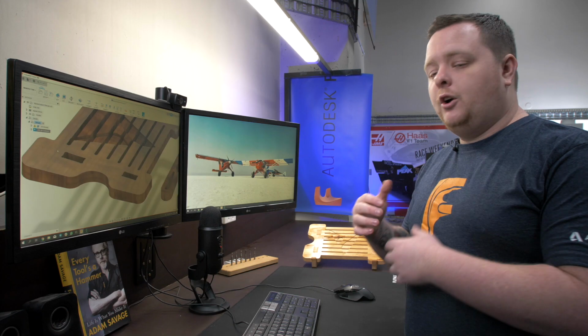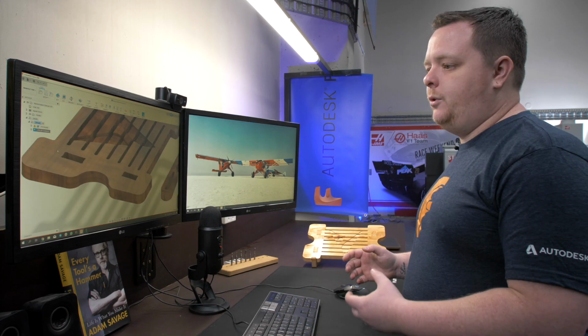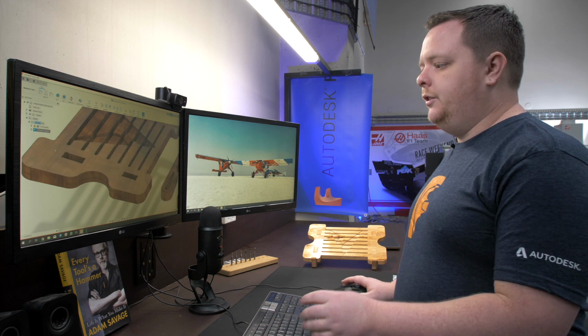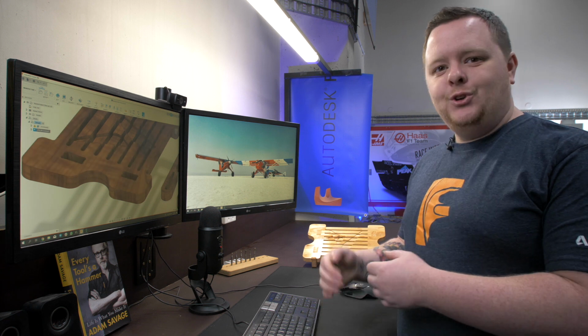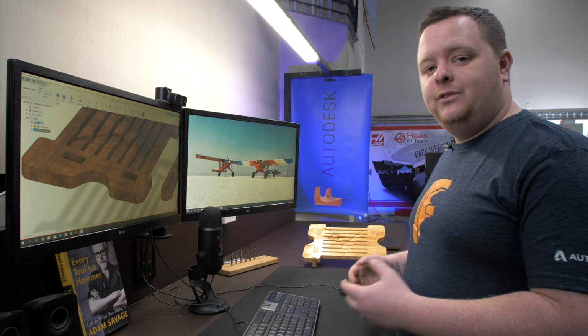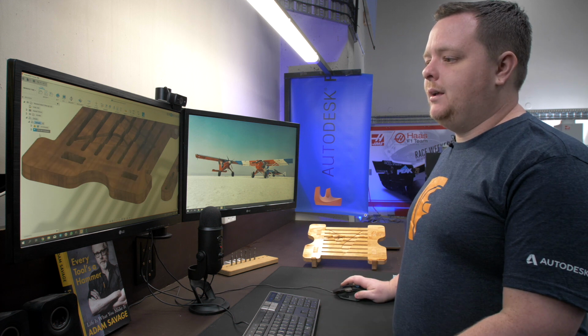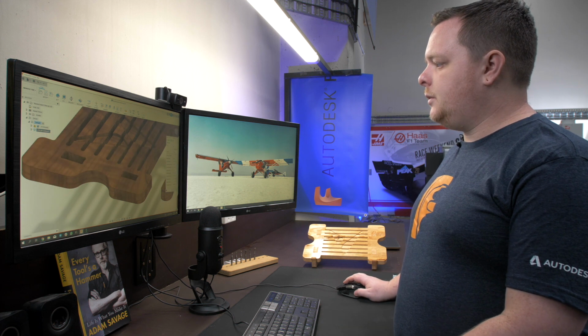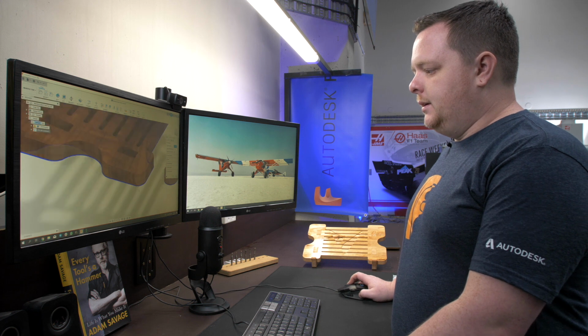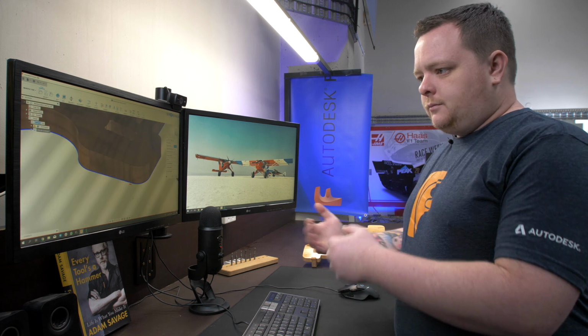So this is a really common problem, and I see it coming up quite a lot in questions: why is it trying to cut the internal side of my part out? Well, it's the direction of the arrow. So make sure you jump back in again, go over to geometry, and just click the arrow. That'll jump it to the other side of the line.